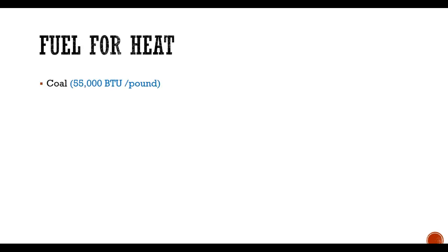So let's talk about BTUs. I want to remind you that 1 BTU is the energy stored in one matchstick, okay? And it's also the energy required to raise 1 pound of water by 1 degree Fahrenheit. So it's really small. A BTU is very little. So for coal, again depending on what kind of coal, you get 55,000 BTU per pound.